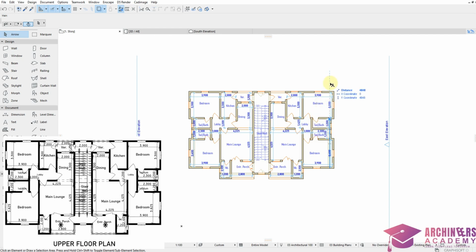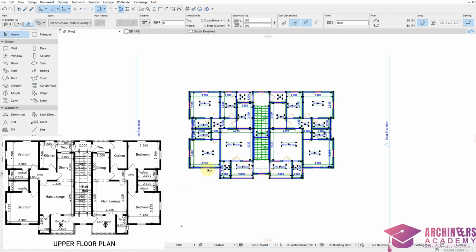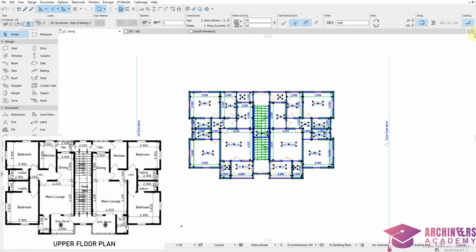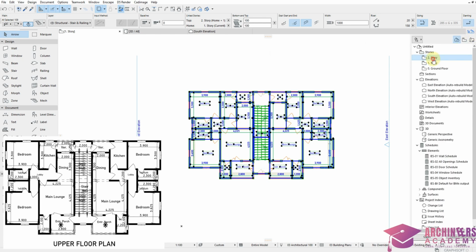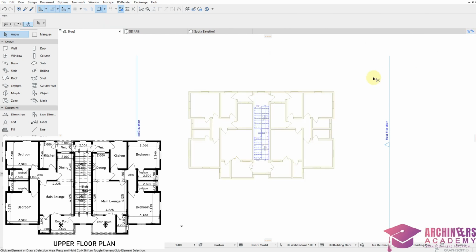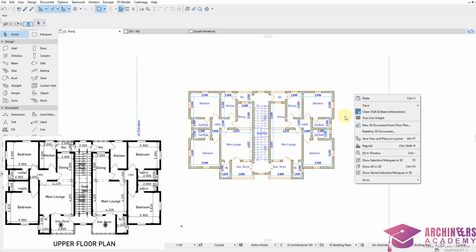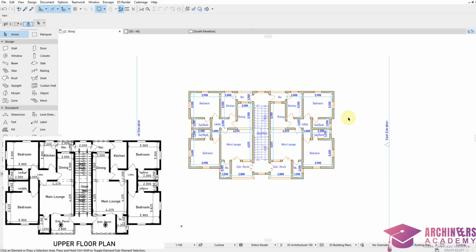So in the floor plan, both the shape and the dimension for the first floor plan and the second floor plan are the same. So we just need to highlight everything here, click Ctrl C, which is copy, or you right click and copy, see the same thing. Then you move over to your second story, open your second story, then you click paste, Ctrl V, or you right click and click paste. You see the same thing. So we have now successfully transferred everything we have in our first floor plan to our second floor plan.